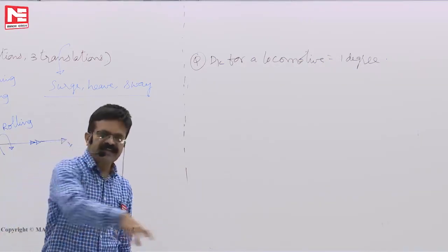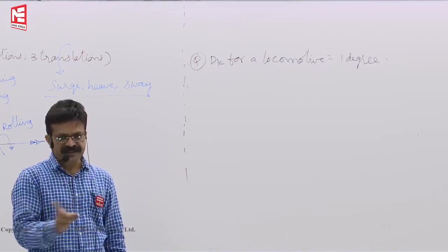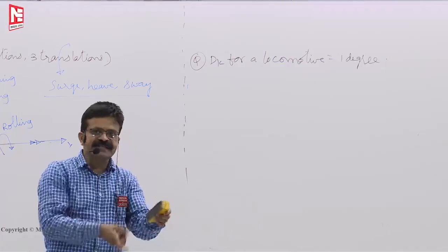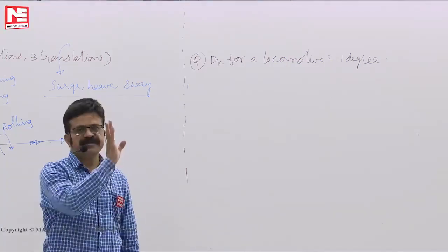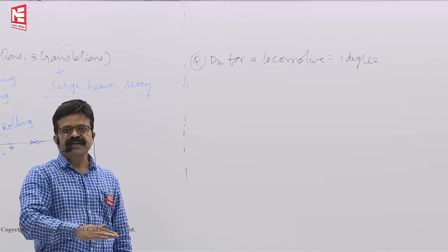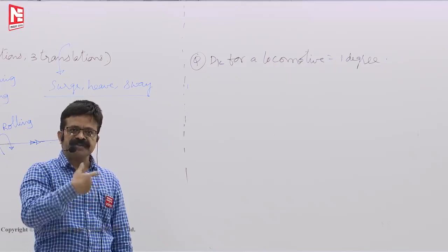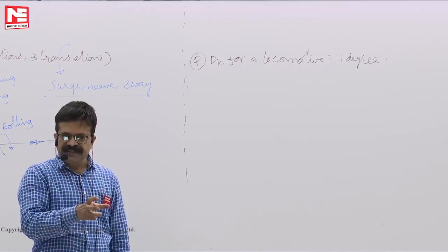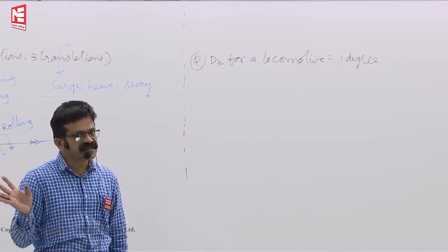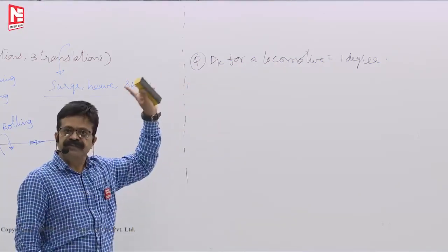It is moving on the railway track. It can move forward, backward, only one independent displacement. Curvilinear motion it can take up, but the radius and theta are fixed quantities, so they are not unknowns. Then upward and downward it cannot move. Leaving the railway track it cannot go up. Moving up means an accident happened. Leaving the railway track and moving horizontally is also an accident only. That is not an independent displacement. So dk for a locomotive we have to consider only one.